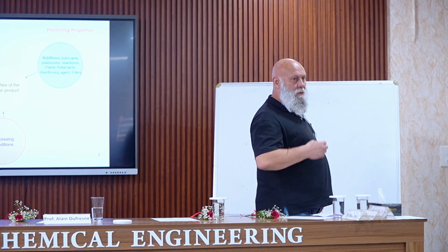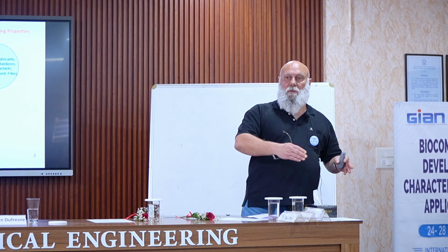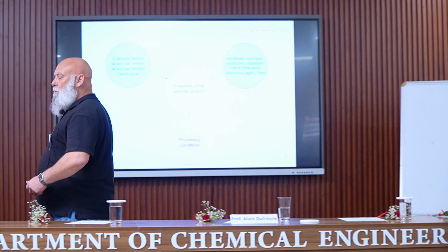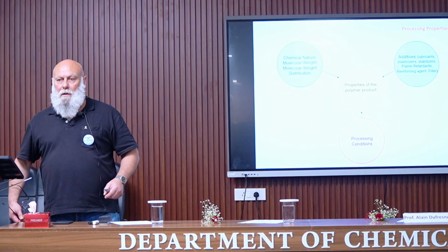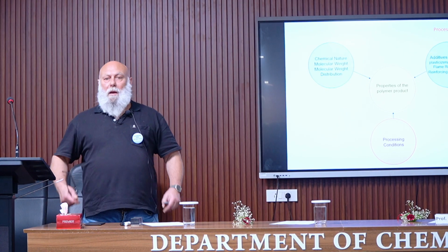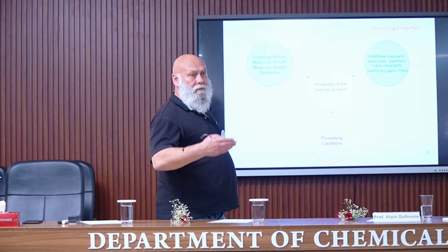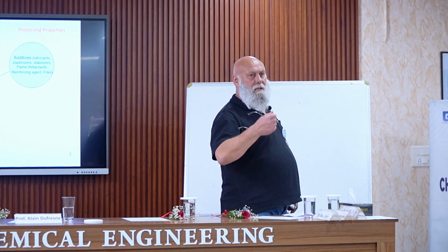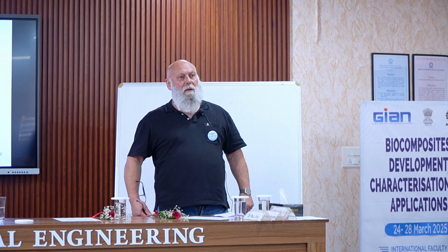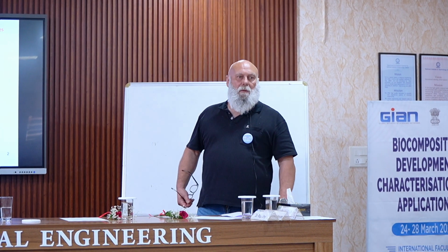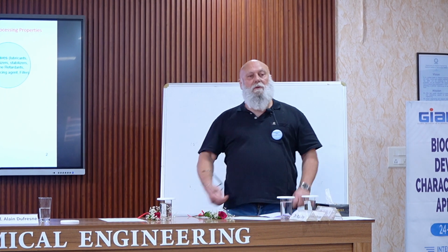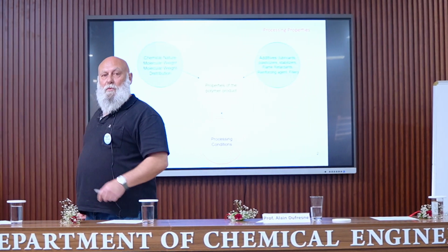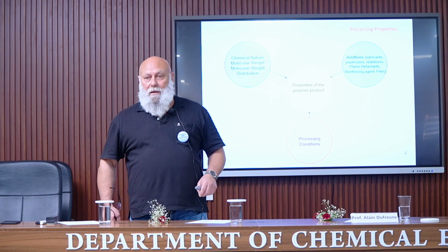So one polymer which is classically used in the form of a plasticized polymer is PVC, polyvinyl chloride, and we have totally different properties because, for example, the Tg of PVC is around 80 degrees, so meaning that at room temperature it's a stiff polymer, but when adding enough plasticizer, we can decrease the Tg, the glass transition temperature, below room temperature. So even if room temperature is maybe higher in Kerala than in France, we have now a flexible polymer.